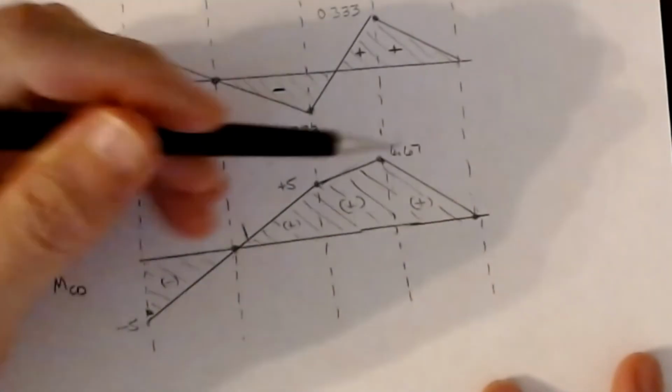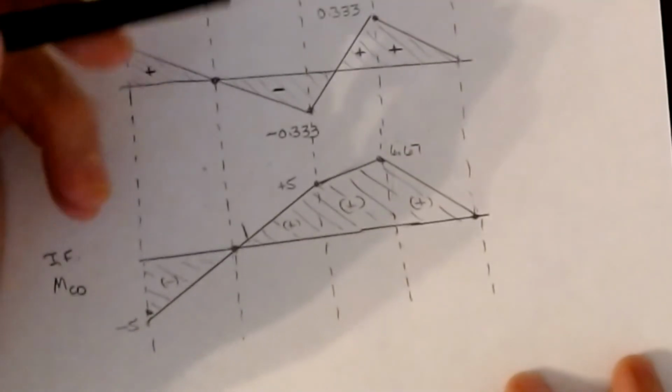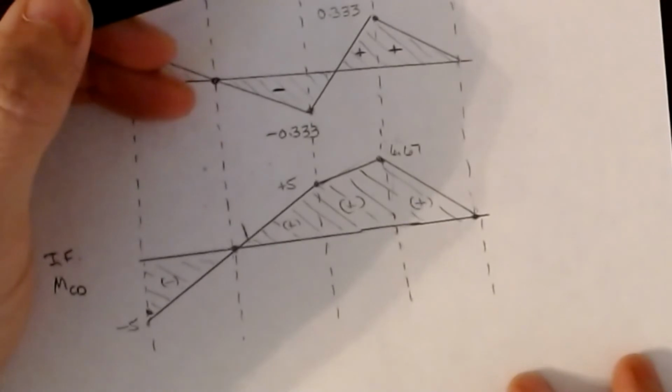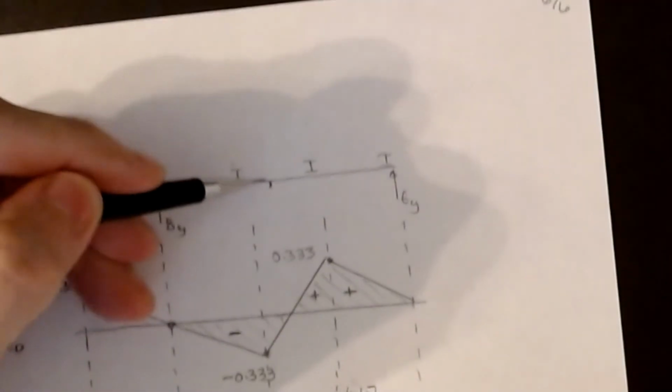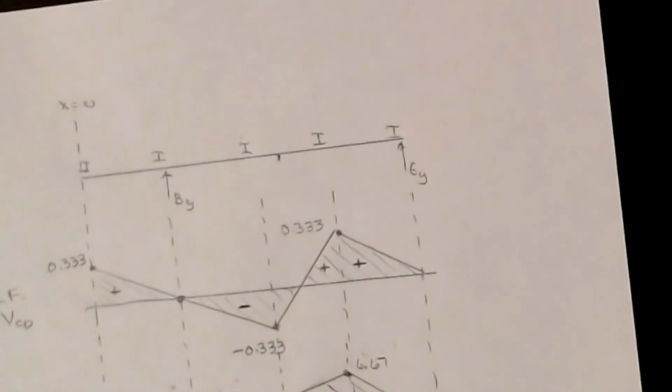But very quickly, you can construct these lines and you can quickly see where loads need to be in order to get the maximum effects that we're looking for, in this case, that point F up here at the midspan of span CD. So anyway, I know we've gone kind of quickly through that. Like I say, a lot of the math you've seen before. It's just a matter of setting up the pictures and understanding how these loads pass around.